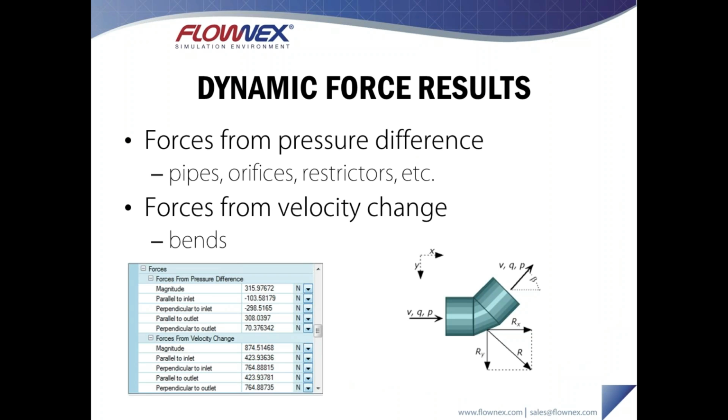In this case, this is available on most of our flow components, so pipes, orifices, restrictors, etc. And then also forces from velocity change and our bends. So we're able to see the magnitude of these forces as well as the individual components of these forces. These become incredibly important in the analysis of the stresses on these particular pipelines.